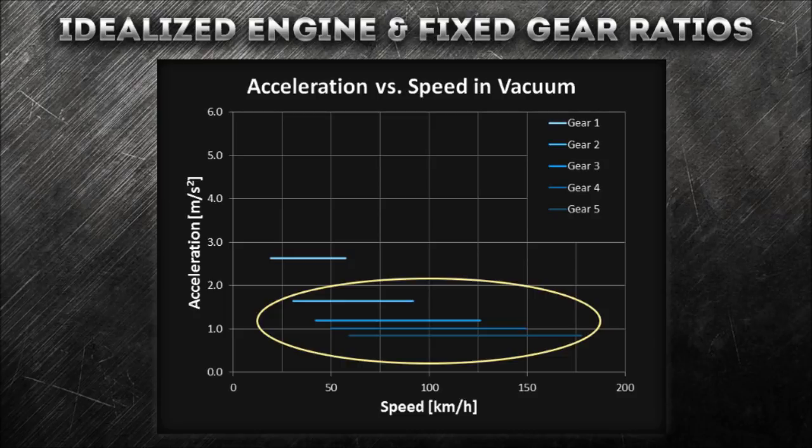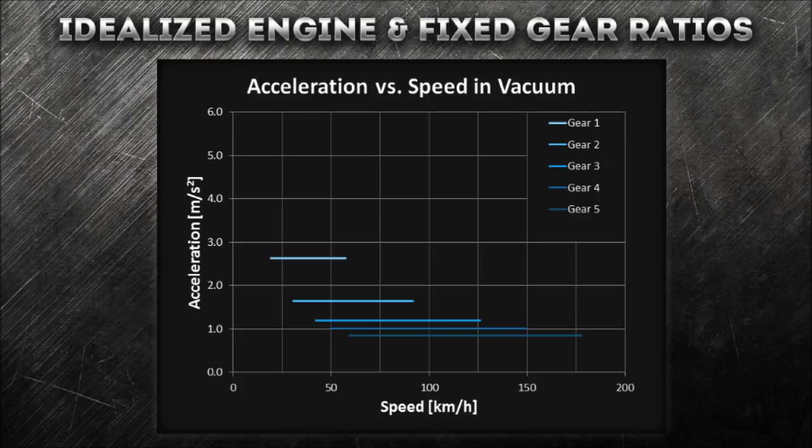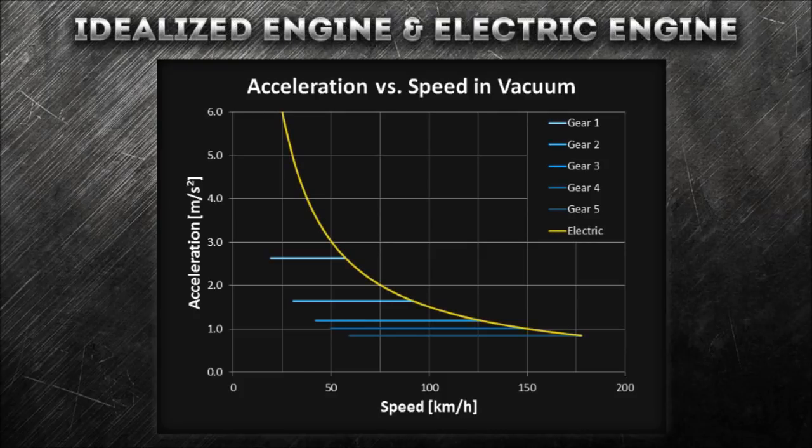That is because the engine runs at lower RPM, which means it is producing less power at the same or higher speeds. It is important to note that ideally a gearbox would keep an engine at peak power RPM at all times in order to maximize acceleration. In that case, the car's starting acceleration would be 3 times higher with a gearbox that accomplishes this, because acceleration at lower speeds takes so much less energy.